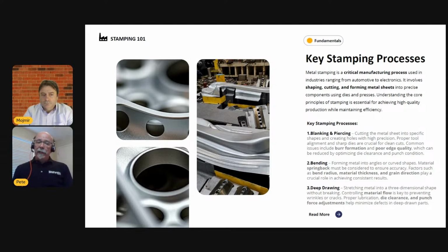So we can't simply offset the clearance between the punch post and the die cavity by material thickness. We have to allocate for the thickening. Some materials, mild steel, for example, and some high strength, low alloy materials may increase in thickness 10 to 15%. But you get into some austenitic stainless steels and you'll see the flange thicken as much as 40%.